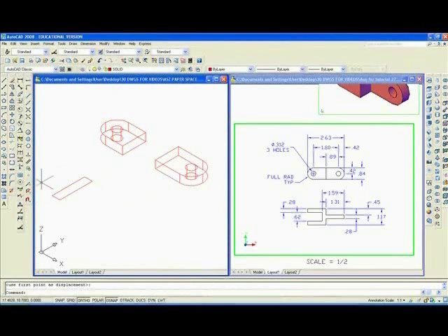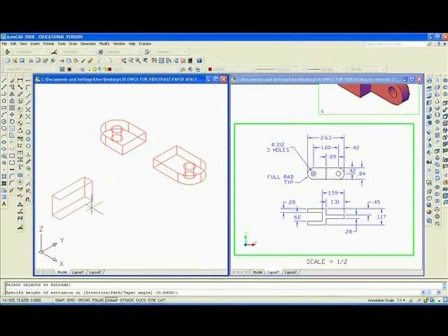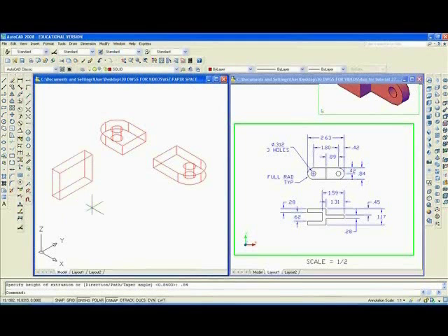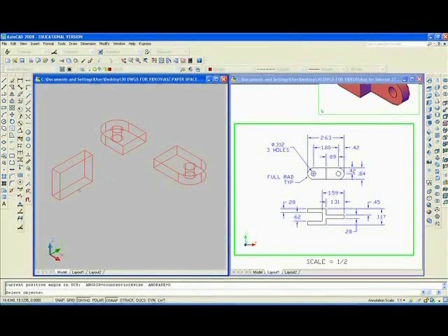Next, I'll want to extrude this rectangular block to a height of 0.84. Enter. Yeah, I think I said I wanted to extrude this to a height of 0.84. Then I'm going to 3D rotate it around the red axis 90.